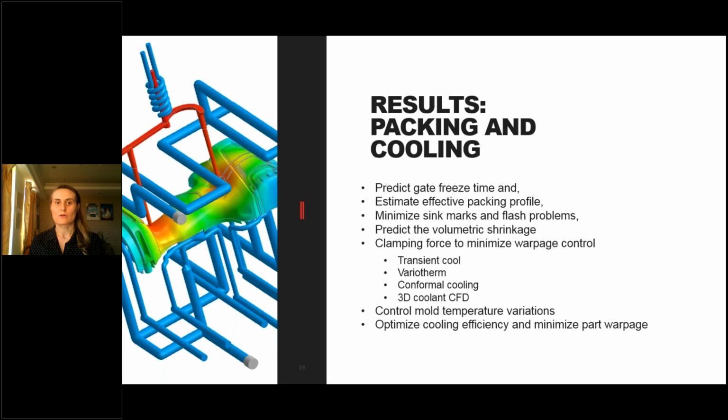In the results for packing and cooling, you would want to see the gate freeze time. Maybe you are overpacking the part and the gate is already frozen. You will want to estimate the effective packing profile, minimize your sink marks and flash problems. You would want to choose the right machine with the right clamping force for your part. And in the cooling stage, you would like to see the cooling system, if it's effective, if it's cooling the part in the right way, and you can optimize the efficiency, which will later on help you with minimizing the part warpage.